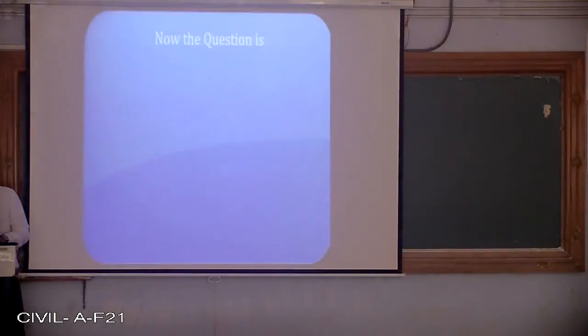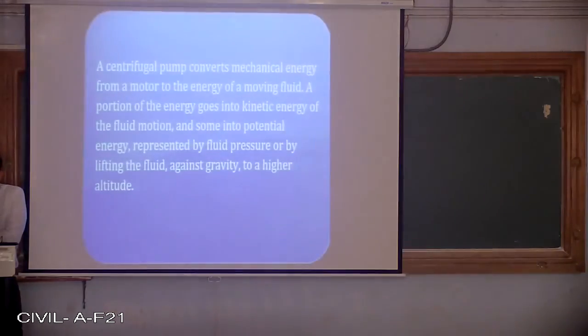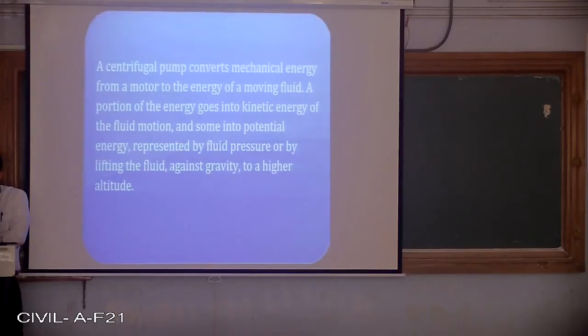Now the question is, what is a centrifugal pump? A centrifugal pump converts mechanical energy from a motor to the energy of a moving fluid. A portion of the energy goes into kinetic energy of the fluid motion, and some into potential energy, represented by fluid pressure or by lifting the fluid against gravity to a higher altitude.